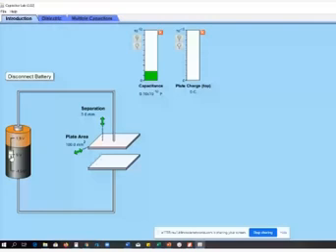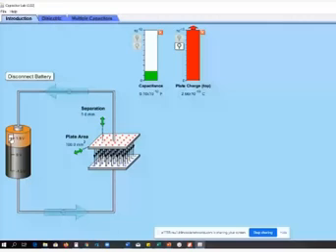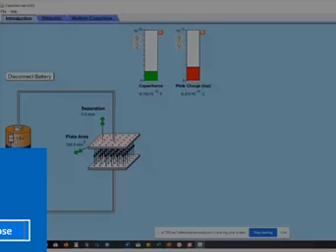And so you move this slider to 1.5 volts. Then you can see I have a value for my charge stored here now. You can reduce this meter so that it doesn't show up to the topmost bar. Is that okay? So I have 0.27 times 10 raised to power minus 12 coulombs. Is that okay? So that is the charge that is stored here.